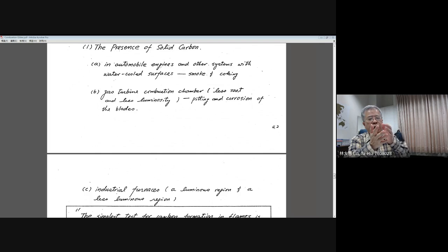Then the liquid attaches to the surface, and you will find they do not have enough time to cut down all the chemical chains to produce carbon and hydrogen atoms. Then the thermal pyrolysis will push all the liquid fuel to become coking, and that coking will produce coke on the hot surface of your cylinder.